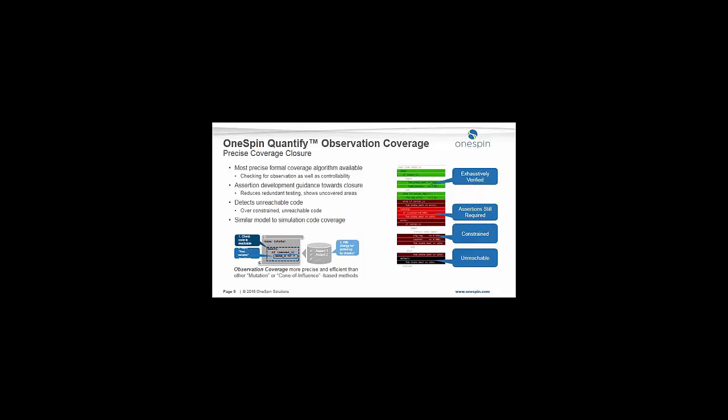So this is covered. But then, of course, it doesn't say whether the testbench checked that the correct behavior was there. So in formal, you can do really cool things built in. For example, here the done signal is mutated to a question mark, which means it can be anything. And then you check on the outside, do any of the assertions fail? If the assertion fails, then it's great. It means you've really covered it by actually checking the observability of a problem. And if it doesn't fail, it means the event can happen, but there is no assertion written to check that this code is actually correct.